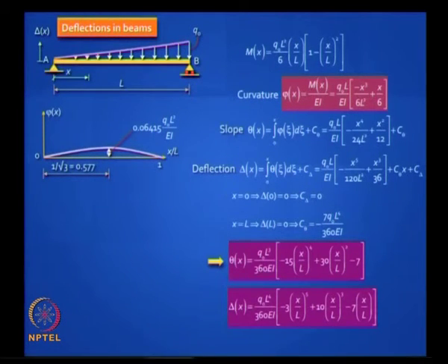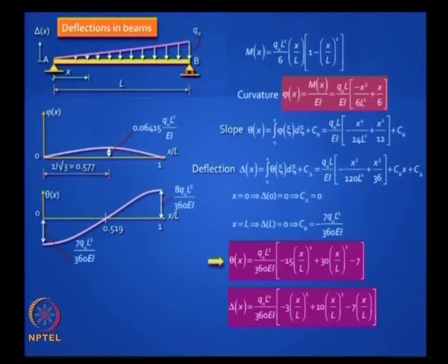No, not at midspan. How do you know where the maximum curvature is? Well, where the moment is maximum. Where is the moment maximum? Where the shear force is 0. So you can locate that point and find that curvature.